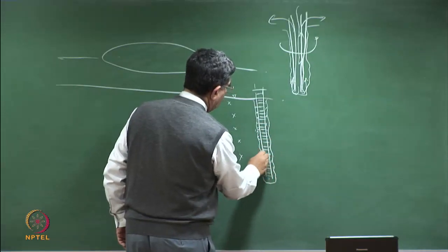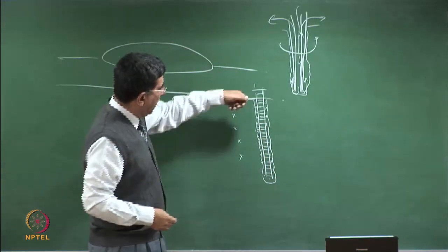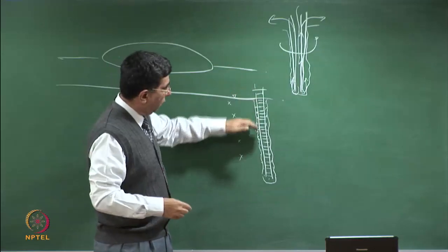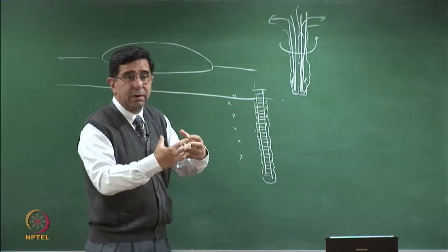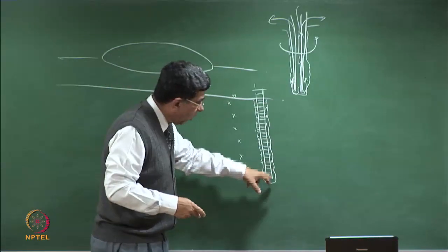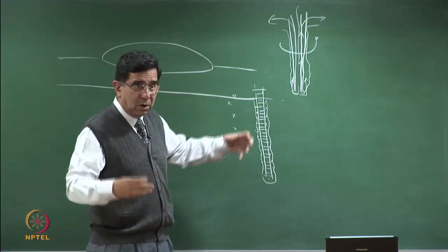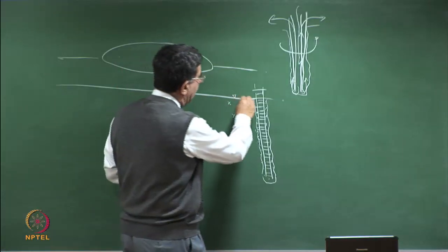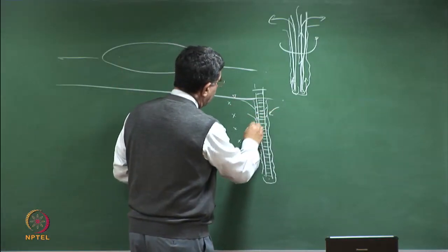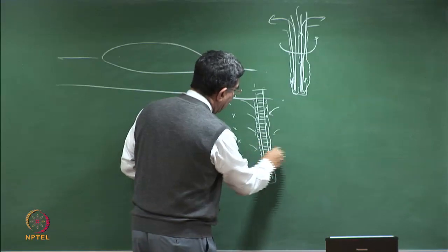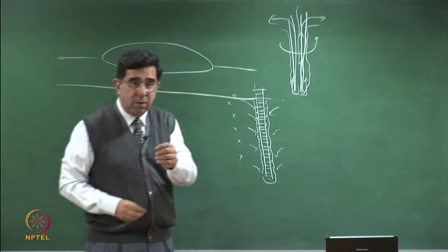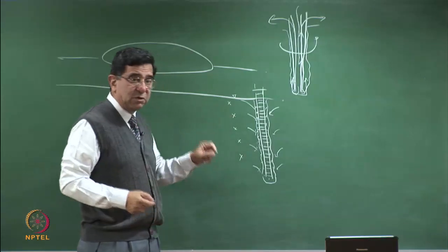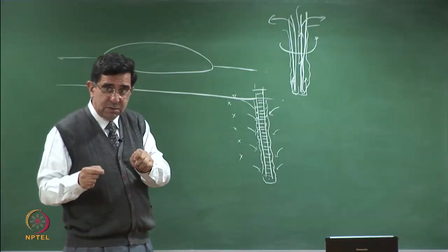So anything you do to take out the water from here, the level will go down. I have to purge 3 to 5 casing volumes, more water will come in. That water will be mixed water of all this, because the water will flow like that. So I am not able to pick up the water from 5 specific points which represents the original condition.